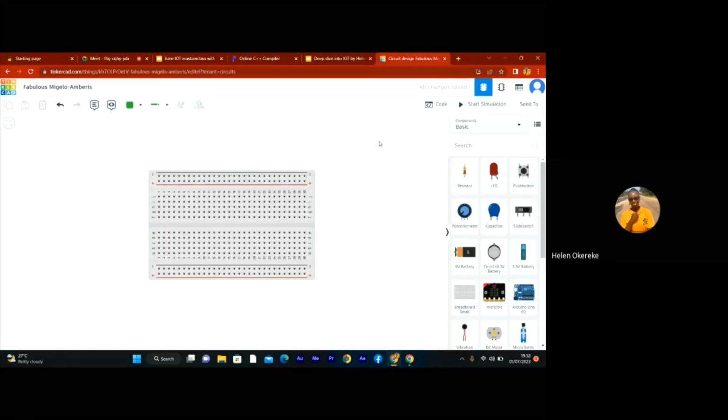So we can take the minus pin of all those hardware devices we want to connect and connect them to this place. Maybe you connect the minus pin of the first bulb here, the minus pin of the second bulb here, the minus pin of the third bulb here, and that is it. Because we have a limited number of pins in the Arduino, the breadboard will help us. All right.